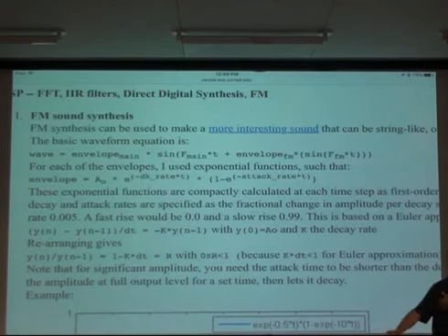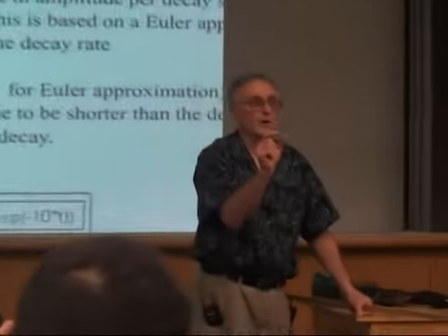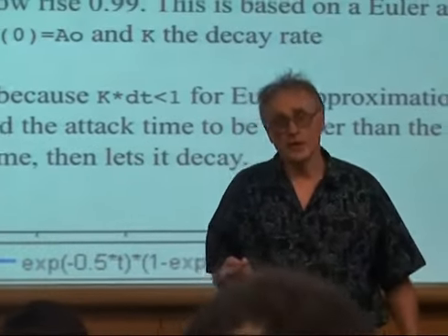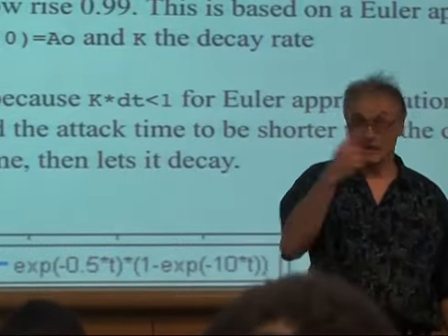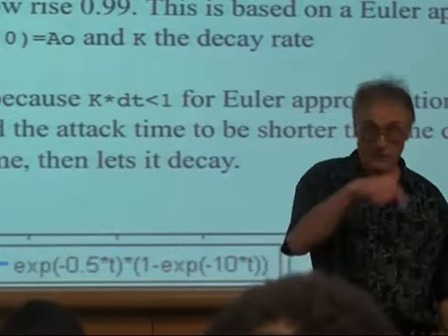Another failure I saw was before the first capture occurs, corresponding to one blade crossing time, people were doing a divide in a high-speed thread that was resulting in a zero period, dividing by zero and failing the thread. So you can calculate that if you set up the motor to full speed, you should get a fan blade crossing in about 3 milliseconds or so, 2.5 milliseconds.